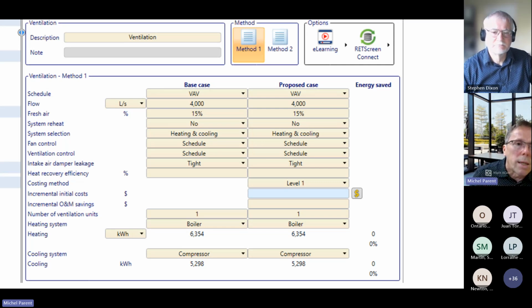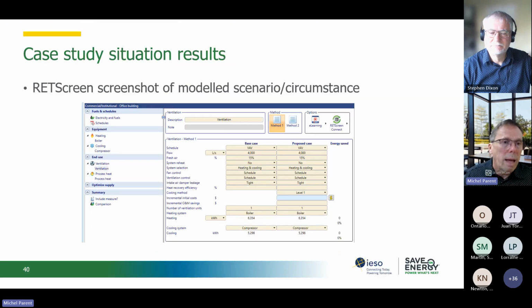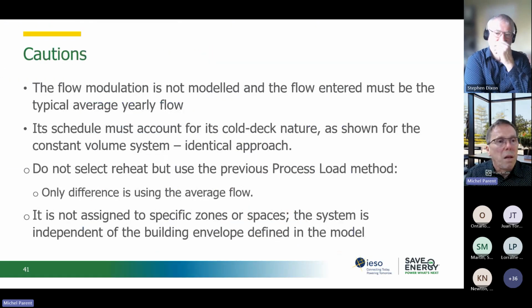The percentage of outside air, just a quick word, if you see on your BAS 15%, take that with a grain of salt. That may not be your true percentage of outside air. Dampers are not linear, so if you can get a better estimate than the percentage you see on the BAS, that'd be great. And then, like I said, the schedule is defined to that VAV schedule. Very, very, very important. The other elements, very similar to what we saw. And basically, that becomes your VAV system.